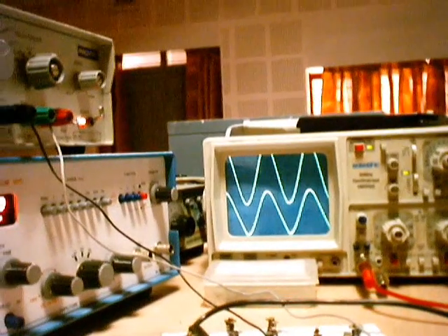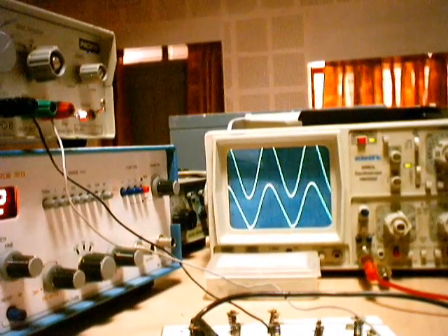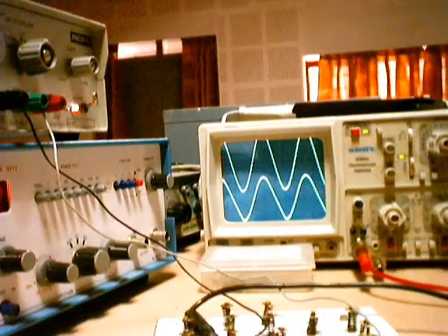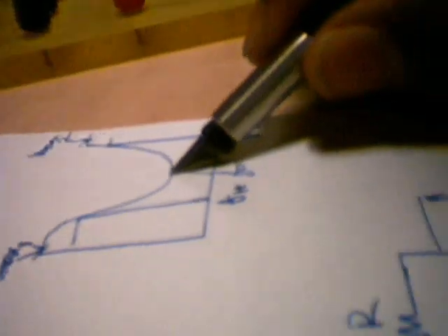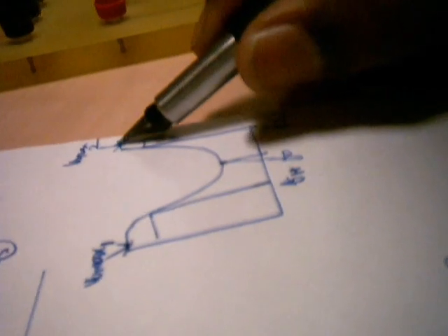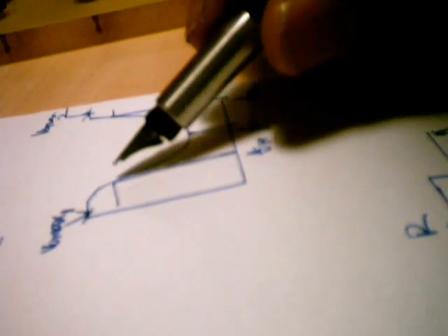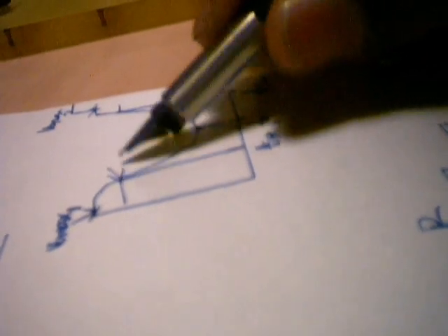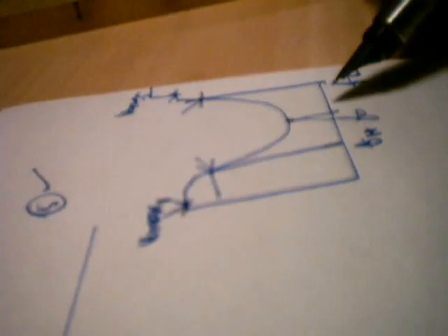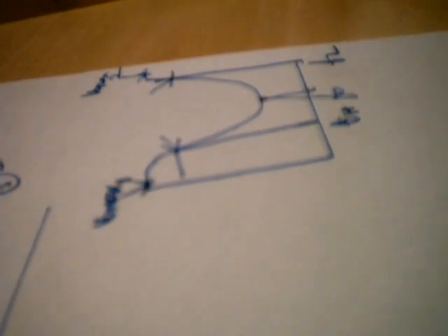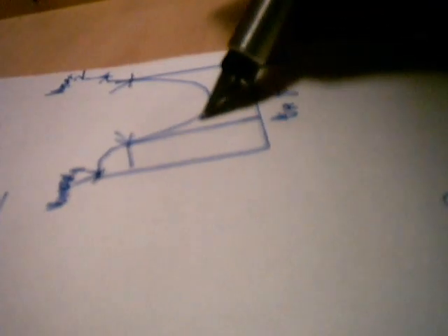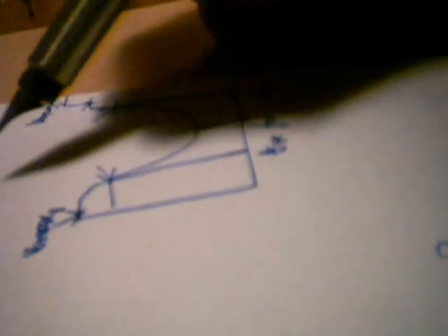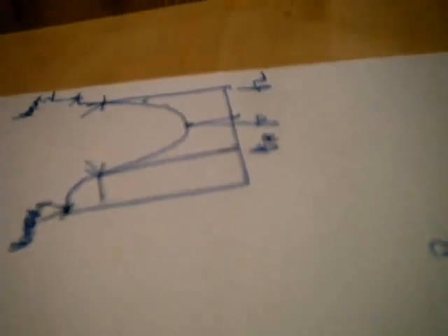Of course, for completeness of the circuit frequency response, you can take a few readings. Now these are the typical readings. We need to take 5 readings: one at F0, one for V0 max 1, another for V0 max 2. The other ones will be 0.707 of V0 max 1 and 0.707 times V0 max 2. So these are the 5 critical readings to find out the center frequency and the bandwidth. You can take a few more readings over here, here and in the passband, so that you can have a smooth graph in the frequency response.